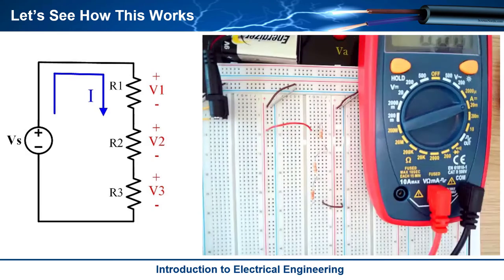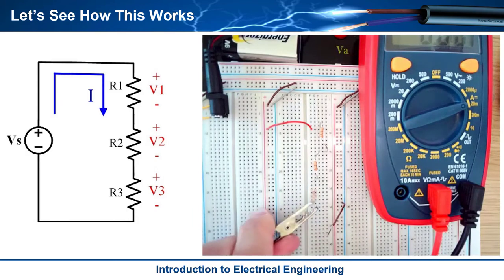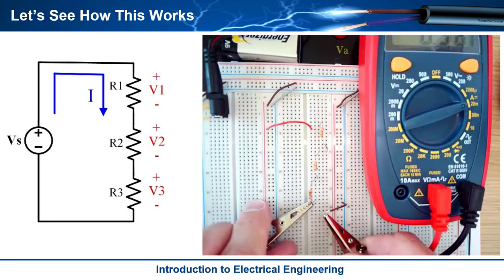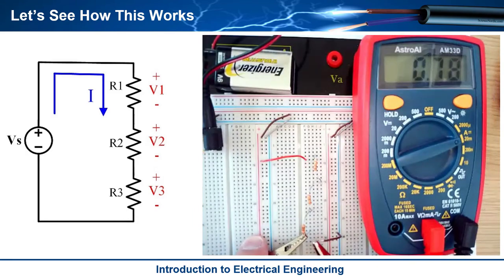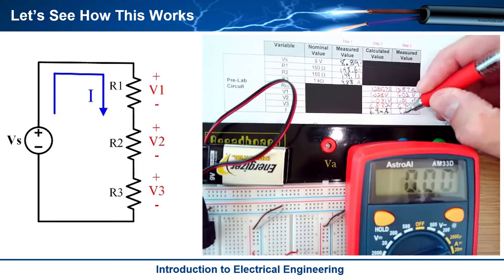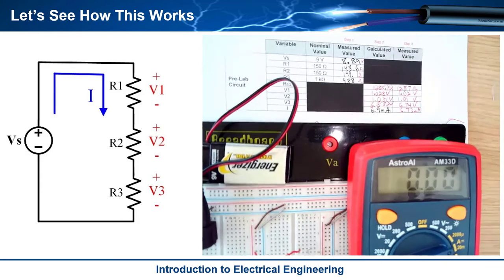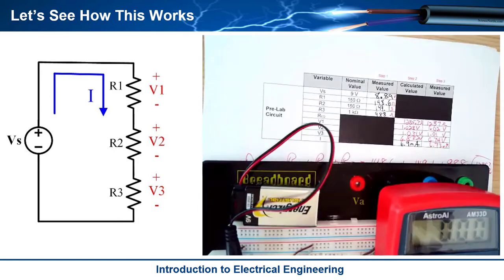What I want to do is break the circuit. So I'll go ahead and pick up here, and I'll pick up there, and let's see what I get. So I clip on, and I end up with 6.73 milliamps. Okay, 6.73 milliamps. I come over here and I get 6.73 milliamps. And look at that. So let's recap what we did.